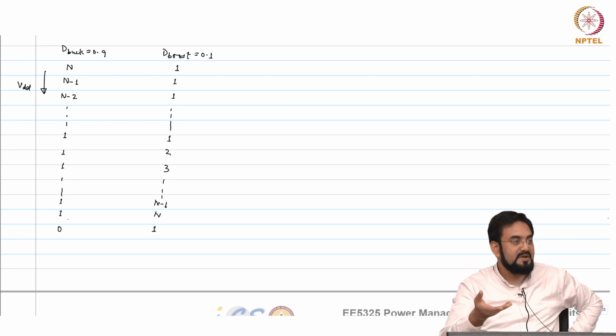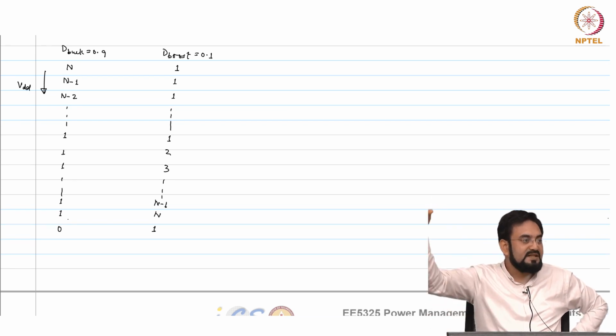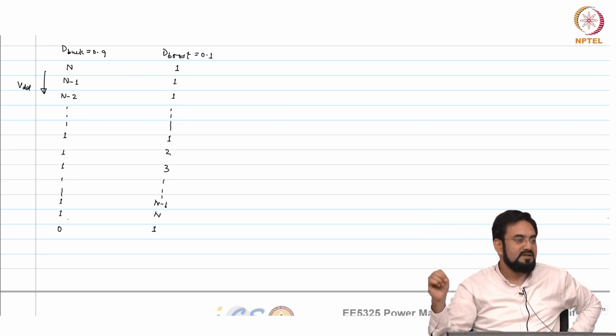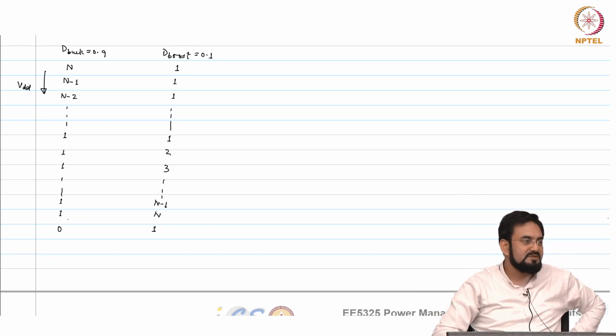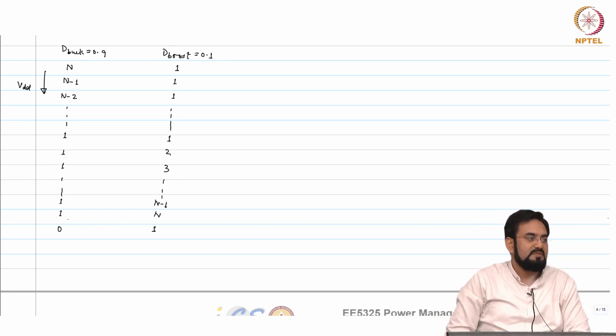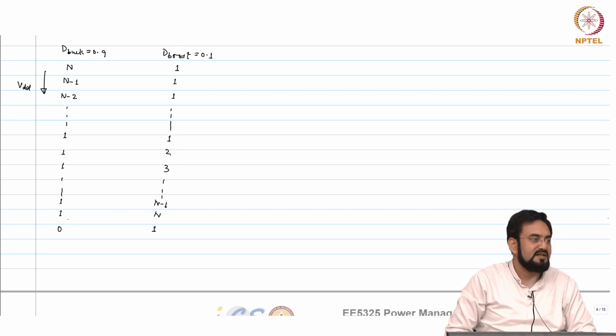This transition may happen during load also. So, 5% let us say margin you have kept for load, and this transition has also happened, so it is quite possible your overshoot may go to 10% or so. But if you have enough margin beyond the load where you can handle this transient due to transition, then you can live with it. You do not have to do anything in that case.